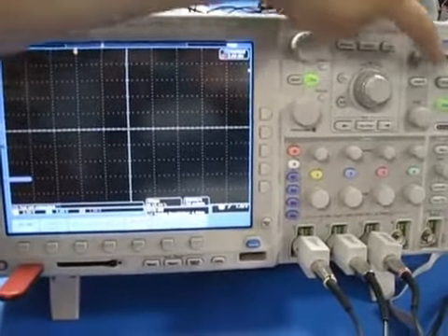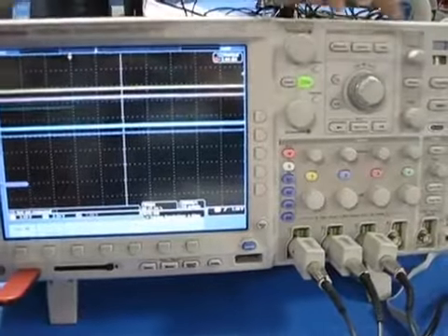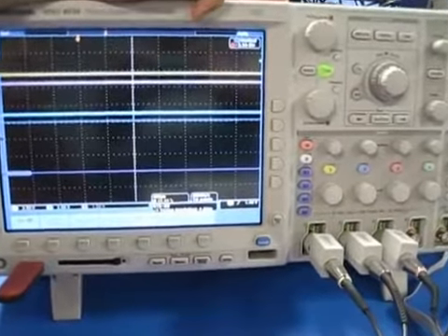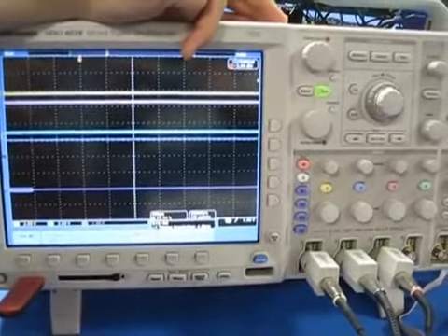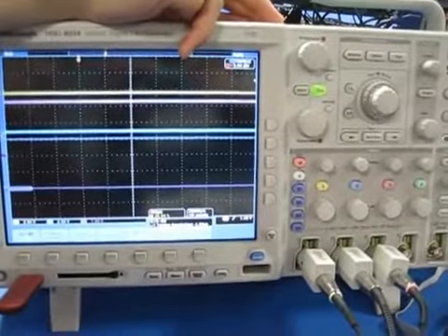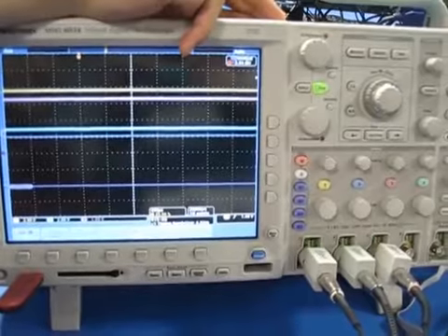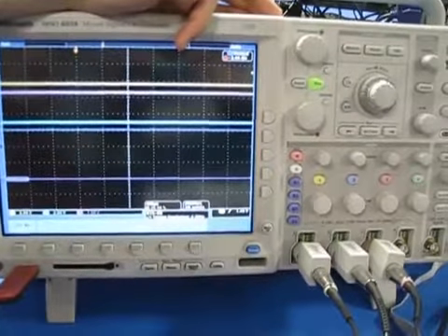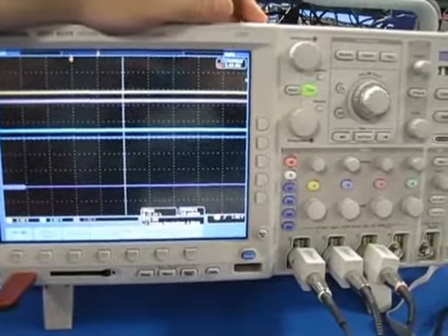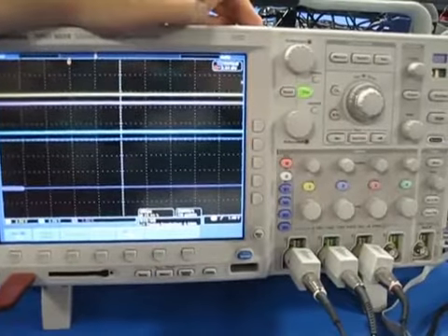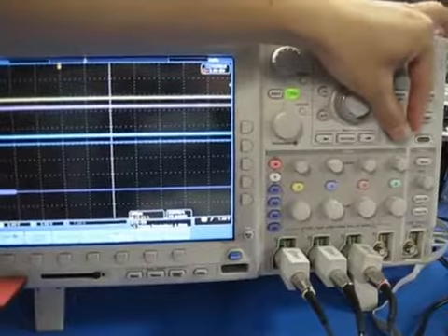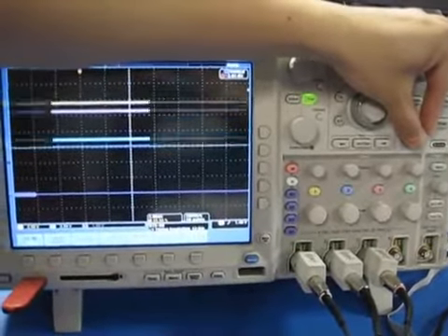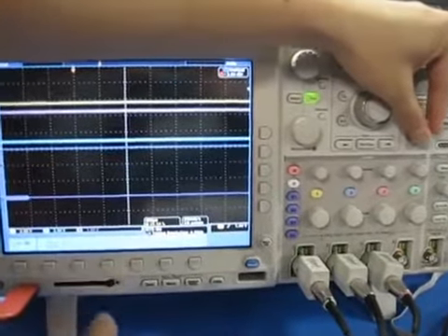I try to capture the whole booting procedure on the SPI bus. Let's take a look at the scope. Channel 1 is used for the clock, channel 2 is the chip select, and channel 3 is the data input, because we want to capture the SPI slave chip sending data to the SoC chip CPU.